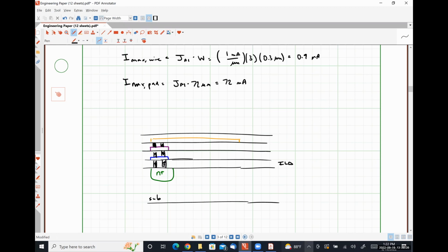So we're not making an assumption that there are metals between the layers. Right, there has to be, just because of the manufacturing process. You're 100% correct there. That is a constraint of the manufacturing process itself. Exactly right. You can't sputter the tungsten plugs accurately that deep.